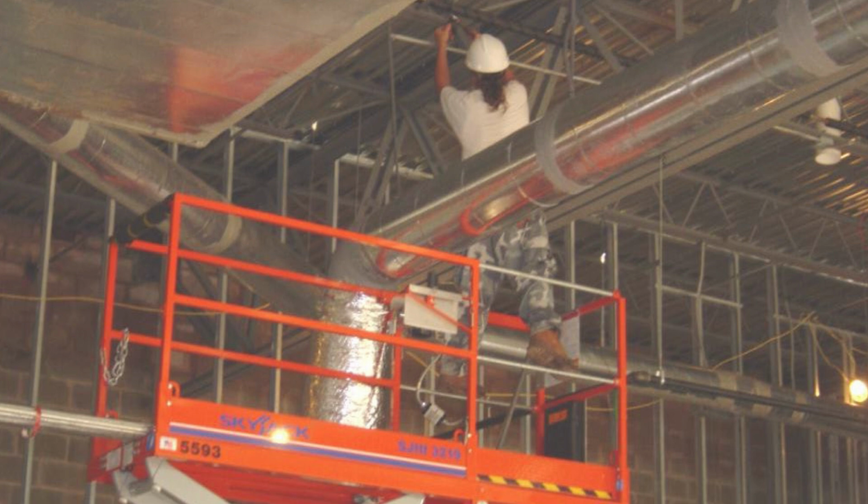Because in this situation right here, if he ties off to the scissors lift and he falls, he could pull the thing down over on top of him, or even worse. So shouldn't he have looked at something to tie off with the harness laying above him? That's what I would look at. But then you got to worry about distances. Can you reach that point and still be tied off? Hopefully, I answered your question. If I didn't, please come back and ask another.